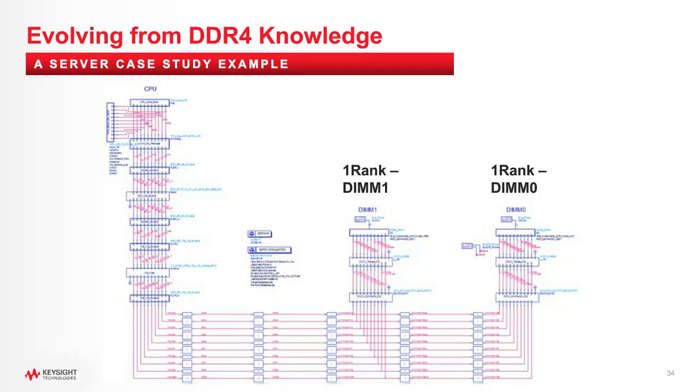And then not only that, but you've got read direction and write direction as well. And then we've got command address lines, control, and data. So it's a very big simulation space to sweep, and we need to approach it with a simulation strategy to make sure that we get good coverage and we compute exactly how much margin that we have.